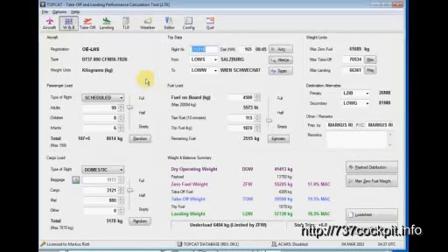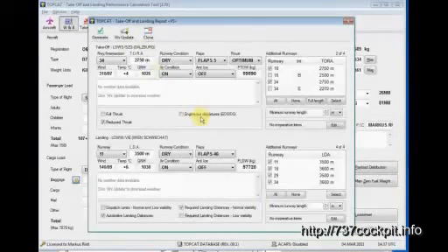This takeoff and landing report will contain our reduced thrust. That means we will not take off with a thrust setting of 100%. We will have a reduced thrust rating. I can show you this report also.